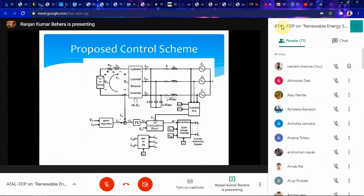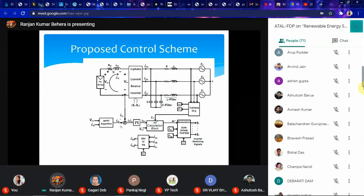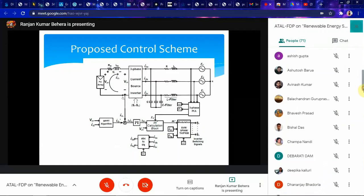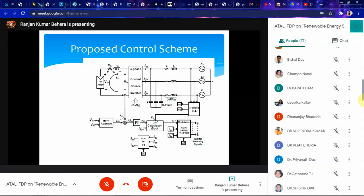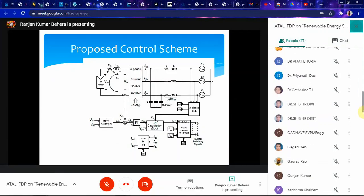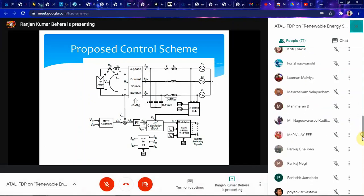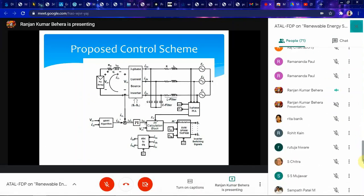So for the MPPT algorithm, you can use this VPV and IDC, both of which you measure with current and voltage sensors. And then in the MPPT algorithm, you take the VDC reference and the measured actual VDC, pass it through this PI controller, and from there you will get the change in the voltage, okay?